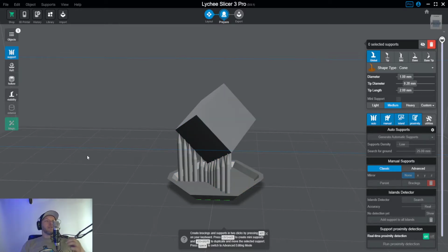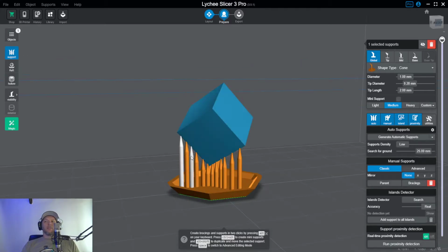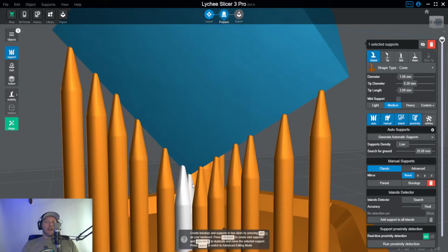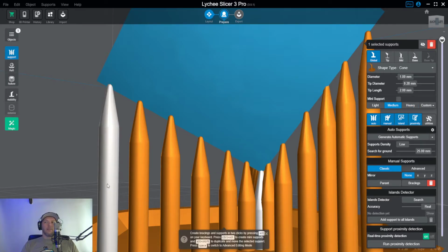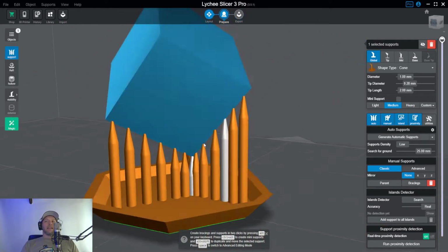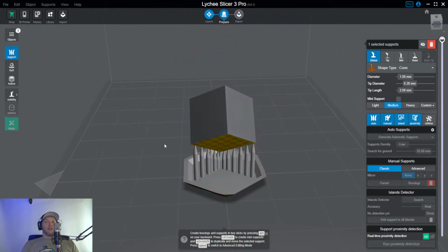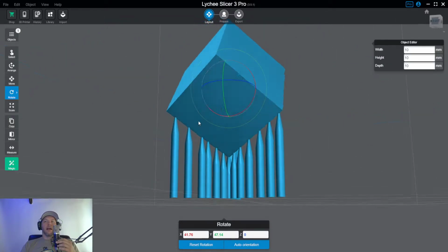And by the time we pull off the supports, we're probably not going to have that much damage because we're using mediums, right? The only one we might choose to have as a heavy is that bottom one, and it's going to damage the tip of that cube a little bit. So you could attempt to use a medium there, but the idea is that we were able to start with a flat orientation and find the best orientation for the model. So we want to remember to start with heavies, support the heavies with mediums, chase the edges, and maybe I can pull up another one where we could talk about chasing an edge. And make sure we get a really good orientation that's going to allow us enough support.